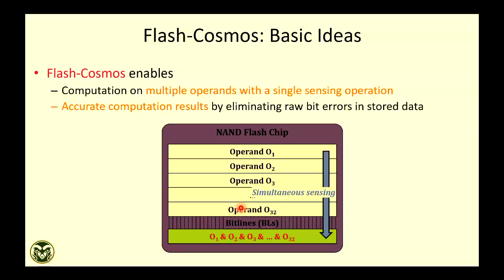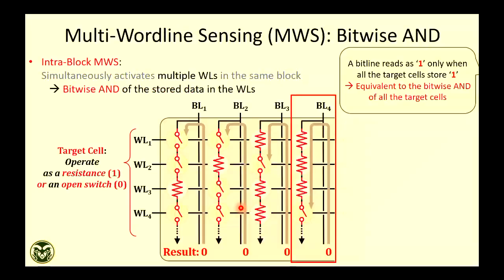Automatically all the transistors will conduct and you get 1. If any of the cells is programmed, there will not be any current. Suppose any of these is storing 0, there will not be any current, so it is 0. That's how you see which string is conducting and which is not, and simultaneously you can do the AND operation. Questions? Okay, so that's their proposal.